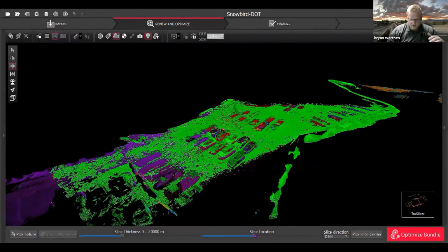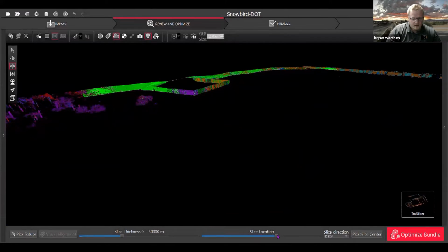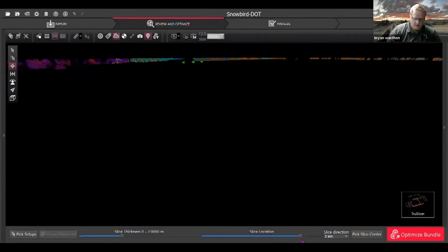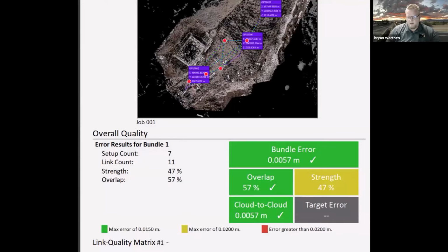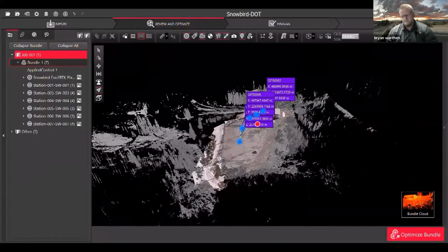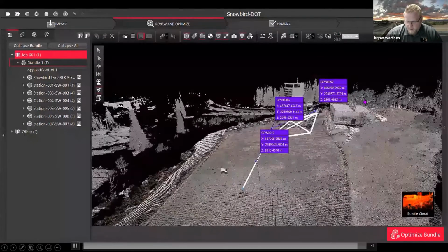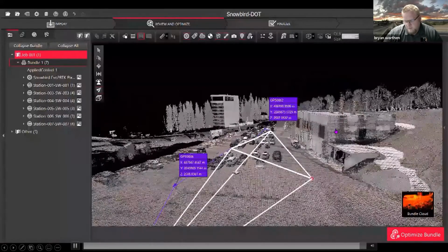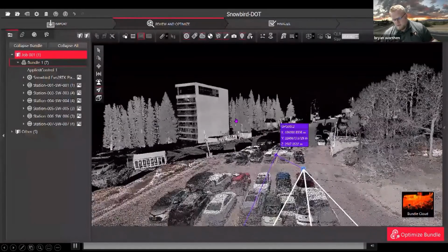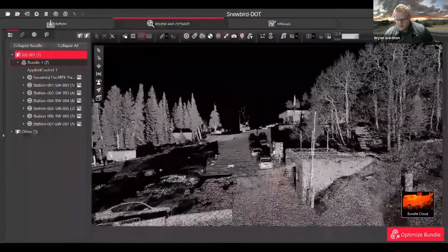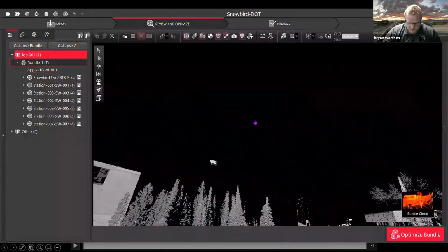And this, I used the slicer tool, and each individual scan was colorized in a different color. Typically, I'd be looking a lot closer to find the slices and the different colors to see how well it did. So that was my final result. And here's just a fly through. I'm not worried about it. But you can see the P40 data is gray. The colorized data is the photogrammetry data, which I don't know if I mentioned. The scanner I used was a P40. The drone I used was the Autel Evo 2 RTK to collect the photogrammetry data.